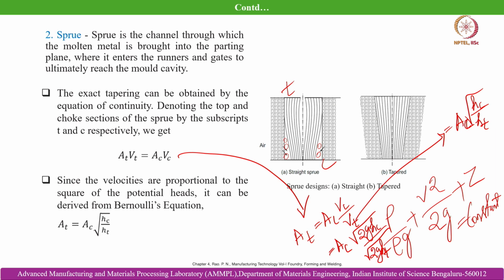That is why we always need to ensure that the melt flows full within the different subsections of the gating geometry. Otherwise, there will be flow separation and chances of air aspiration, which can cause bubble damage or defect formation within the cast part, significantly downgrading its mechanical properties and structural integrity.